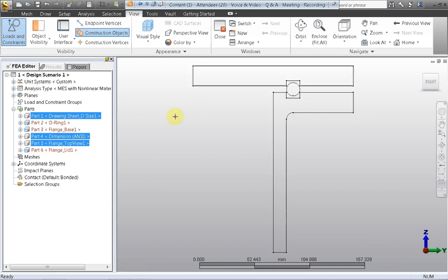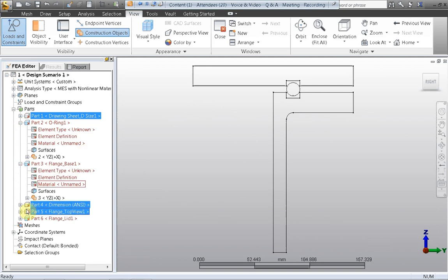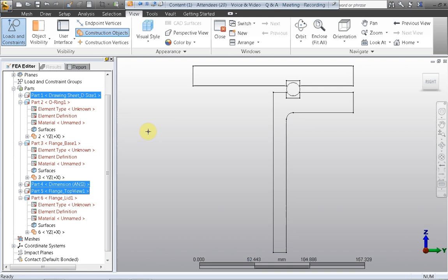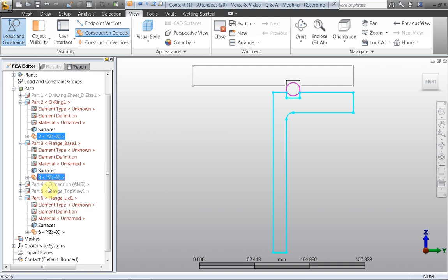Okay, we now mesh these. If you've got an analysis that is axisymmetric or symmetric of any sort, it's much easier and quicker to actually analyze it in 2D. It's faster, gives quicker results, and also it's easier to create 2D geometry in certain instances to do the analysis on.